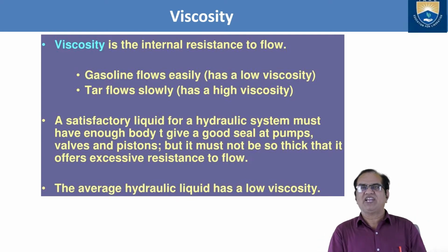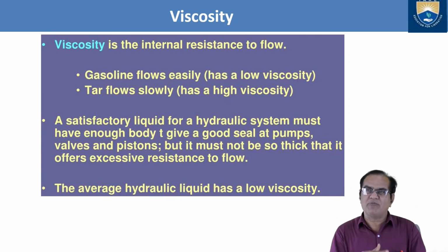A satisfactory liquid for a hydraulic system must have enough body to give a good seal at pumps, valves, and pistons, but it must not be so thick that it offers excessive resistance to flow. So the fluid should not be as thick as tar. The flow will not be there. It will stop the flow.